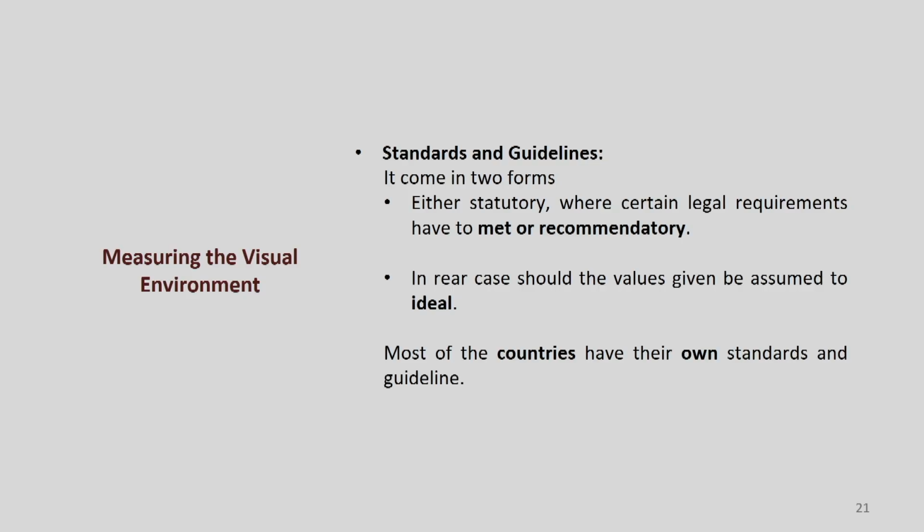Maybe you have a guideline. If it is an office area, approximate lighting may be 500 lux, but is it general for all types of office? Definitely not. What work people are doing over there, based on that you can make changes, you can do an experiment, and you can publish that particular data for further reference.